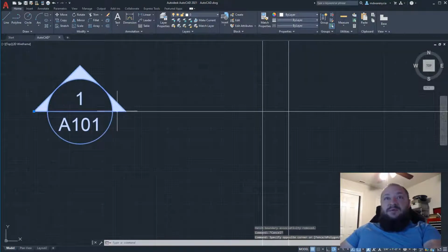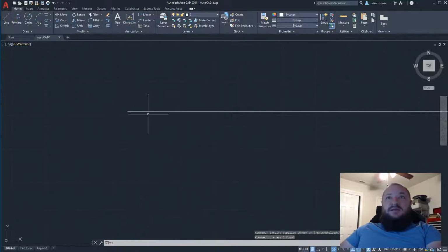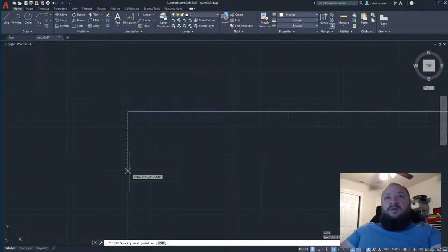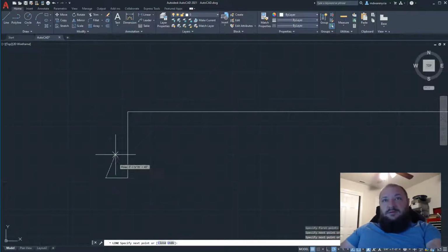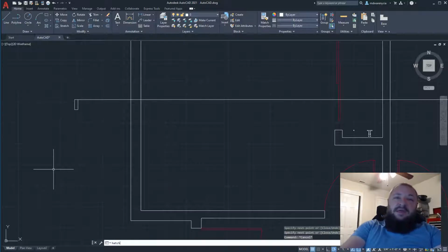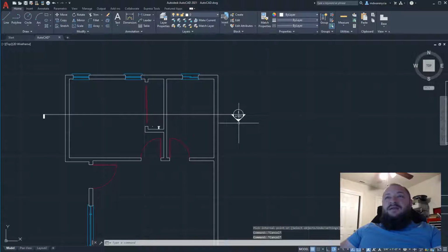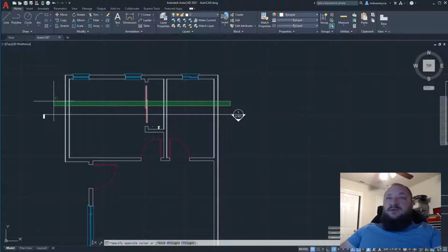Sometimes people will only have one of these on one side, so there are cases where you'll see a section cut marker with just like a little rectangle thing off to the side here, and then with the hatch, and this is just an indication that this is the other side of this section cut marker. So you could do either way. I'm fine with that, not a concern of mine.